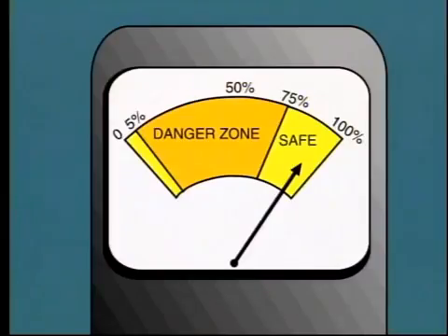Are there any dangers involved in handling hydrogen? Well, the answer is yes and no. For example, a small leakage of hydrogen into atmosphere presents no danger at all, as the hydrogen is completely diluted by the large quantity of air surrounding it. Also, at the other end of the spectrum, pure hydrogen cannot ignite, and so presents no danger. However, certain mixtures of hydrogen and air do present an explosive mixture. The danger area for an explosive mixture is within the range of 5% to 75% hydrogen in air.